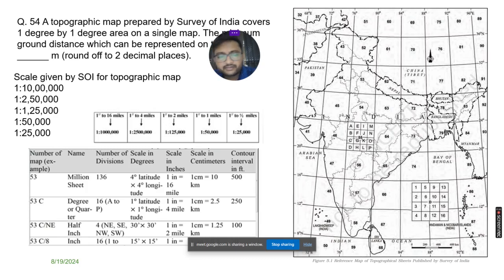Then when we talk about these different topo sheets, if the topo sheet number is 53C8, it means that 53, you first have to locate the number 53 square. Then in 53, there is a subdivision from A to P. So you have to locate A, B, C, D, E, F, G, H. So you locate C. And once you have C, you will have something like this, which is presented below.